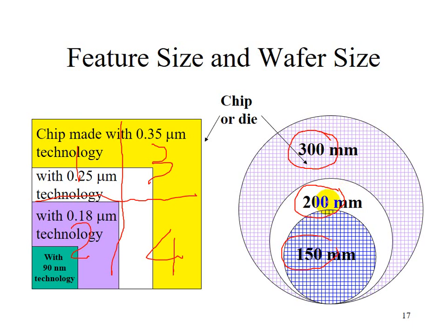The larger the wafer size actually can increase your throughput of chips, also reducing your cost. So both increasing the wafer size and reducing the feature size can reduce your cost. So this is the direction in which technology develops.